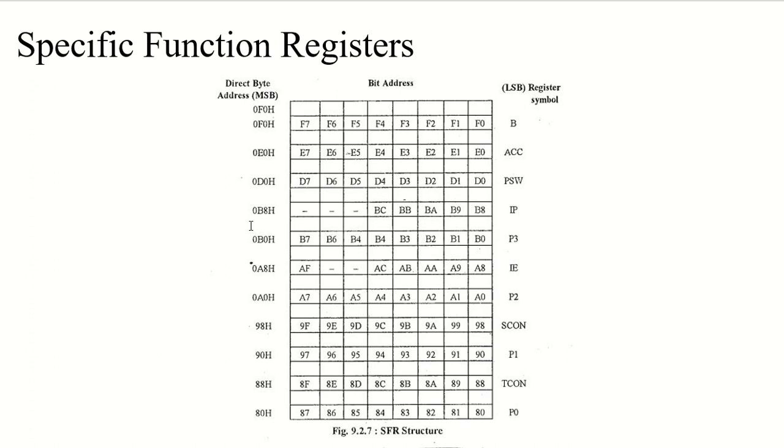So the SFR memory consists of important registers like the accumulator, the B register, the interrupt control registers, PSW, the timers and counters, the power control, the input output ports, and the serial ports. All these internal registers are operated by SFRs, and some of these registers are bit addressable while the remaining are byte addressable. So you may have to check whether the register you want to use is bit addressable or byte addressable.